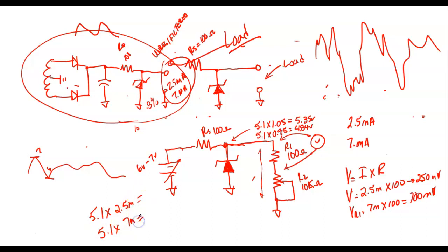That's the wattage this guy can run. So Zeners by themselves are not designed to handle high power demands. But if I needed a real low power supply, then this right here would be great. If I need more power, then we're going to have to add other stuff to the Zener.